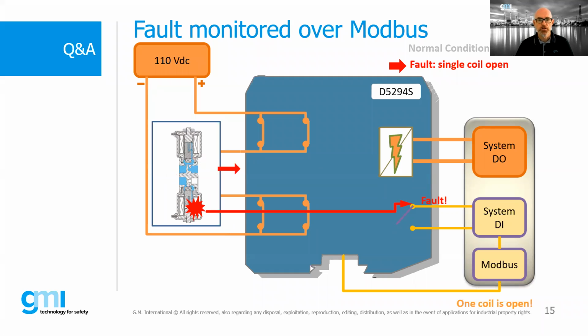Another advantage is the possibility of not using a dedicated digital input system to monitor alarms. This allows us to have significant savings in terms of cost, and real-time information on the type of alarm and on the health of the load and the line. It's also possible with Modbus to do complete remote programming of the relay.